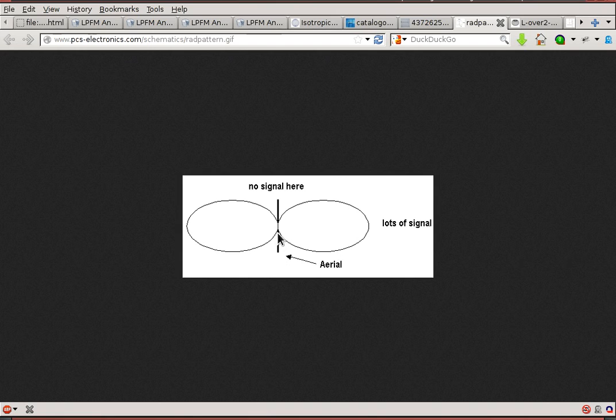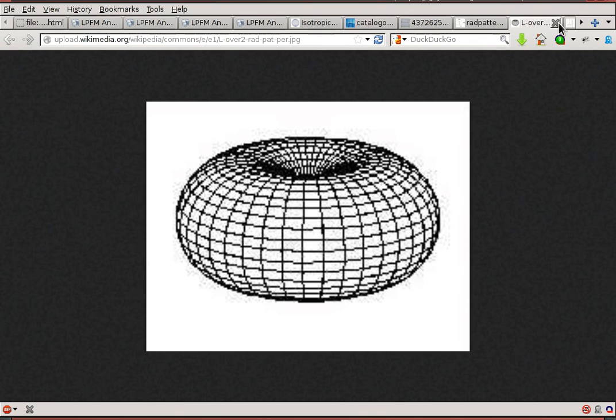And you can do some sophisticated math, some trigonometry and such, and work with this pattern and figure out how much higher the prohibited zone comes off of the ground. This is for those cases when you want to make that case to the FCC that the prohibited zone doesn't touch the ground. And like I said, well, the dipole antenna is probably the most ubiquitous realistic antenna that people might use, but there are plenty of other antennas that are commonly used in broadcasting.